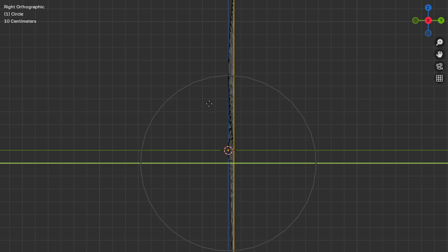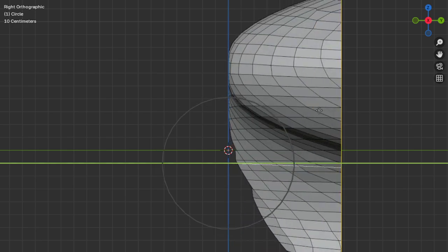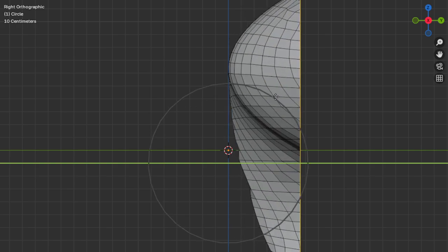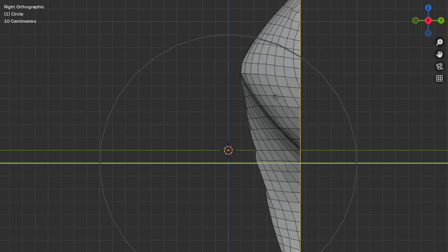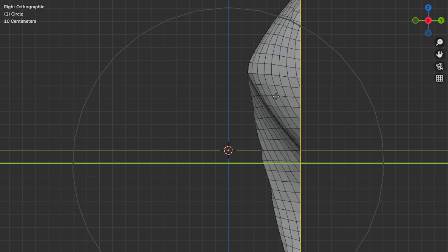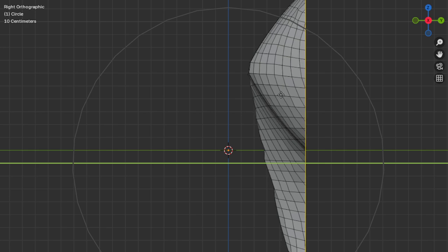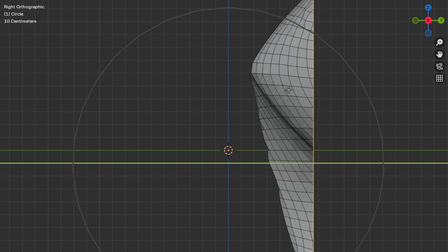Scroll the middle mouse button in the upper direction to decrease the influence area so that you can see how it is. See, when I increase the circle, this gray color circle, which is called the influence area, wherever I am pulling these yellow color selected lines backwards, the embossed shape also follows the yellow color selected edges.